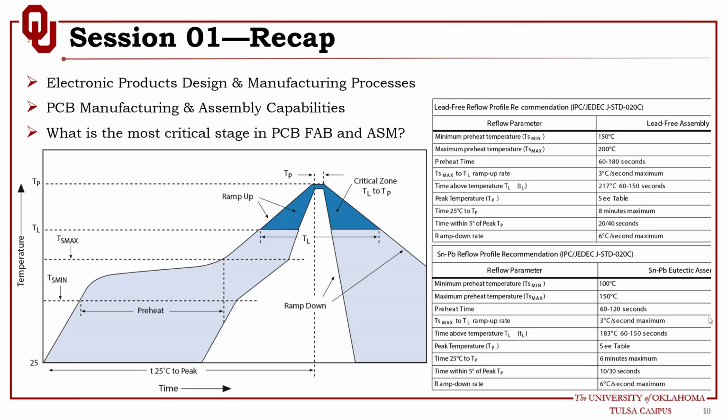So if we take a look at the table here, we have the lead-free reflow profile. This is the default for lead-free assembly, and these are defined by the IPC standard. And this one is for leaded solder, and this is the process, also defined in this standard. And these are the maximum temperatures you can use on the profile.